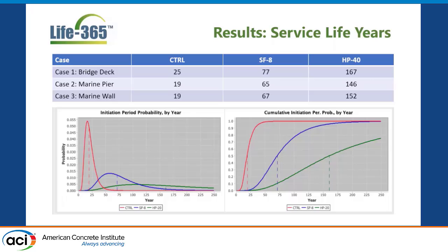There's a lot that needs to be done in terms of sensitivity analysis: which factors matter, which one can I forget that I don't need to worry about. I change this one 20, 30, 50%, and it doesn't do anything to the service life, or it changes it a little bit. I change this one factor and I get big, big changes. It speaks to the need for better or new lab results that get you into the part of the service life prediction that's not being modeled well. Any questions about these results, the assumptions behind it, that part of it?